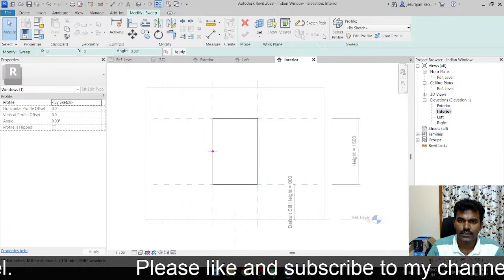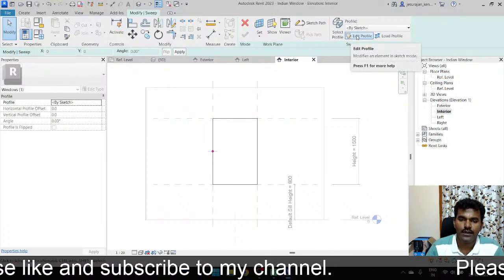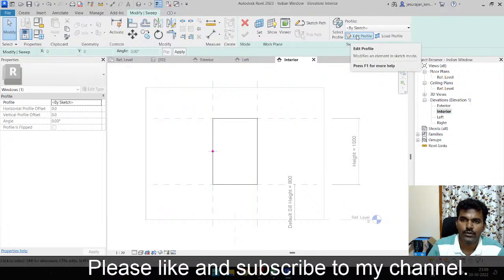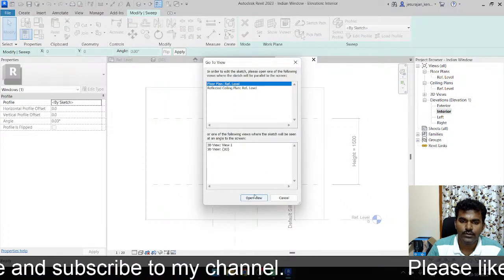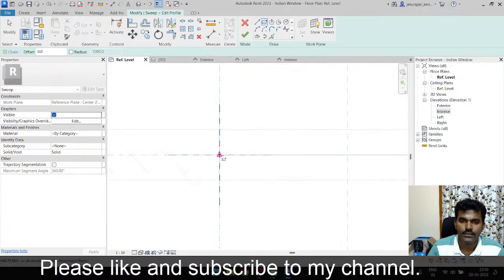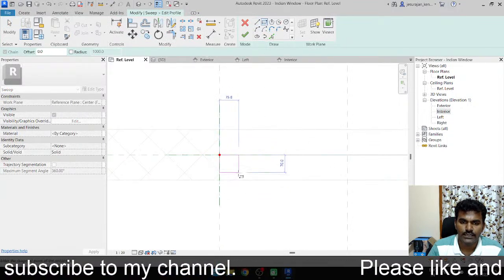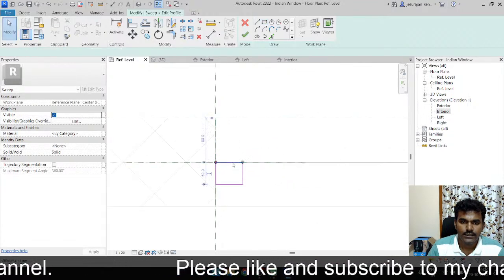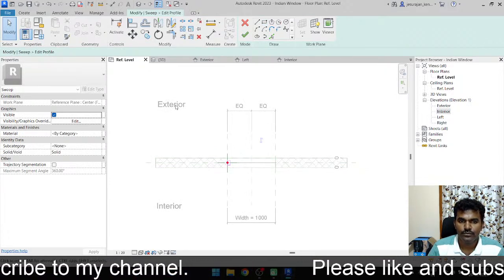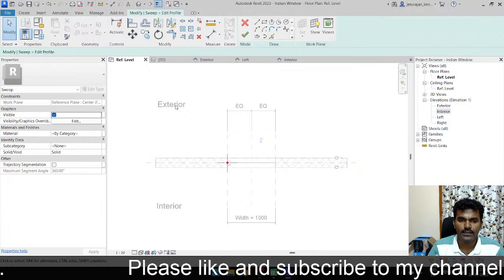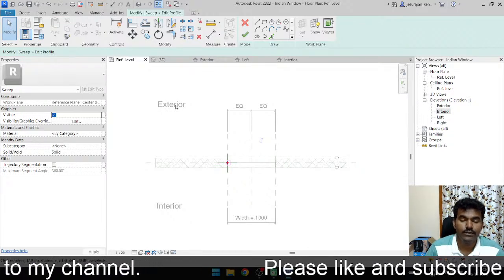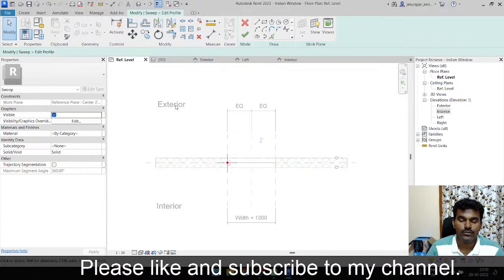Now I'm going to add a profile. So far I don't have any profile, so I'm just going to make it in place. I'm going to edit profile, go to reference level, I can draw anything. Which side is interior, which side is exterior? We want to decide whether to swing our window panel inside or outside. Mostly it will be outside.